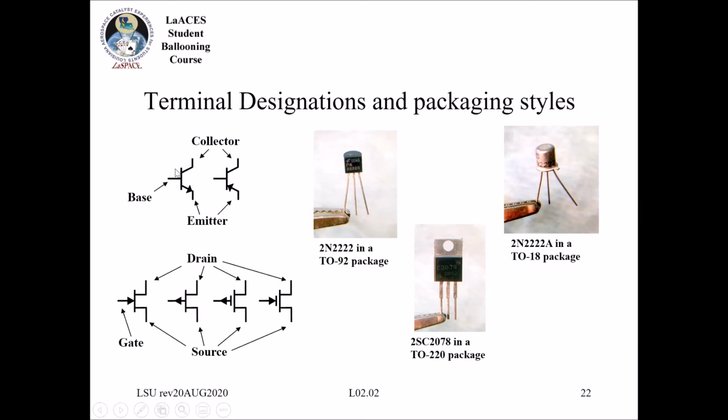But in general, their terminals are also named a little bit differently, and I'm just going to go over them briefly. So you've got the base, emitter, and collector. The base is this one coming off in the center, the bottom is typically the emitter, and the top is the collector. The way this typically works is you apply voltage across the base to the emitter ground, and basically what it does is it will short circuit. There's a linear effect that happens with current, but eventually if you saturate it, the collector will be tied electrically to the emitter, and current will flow across those.